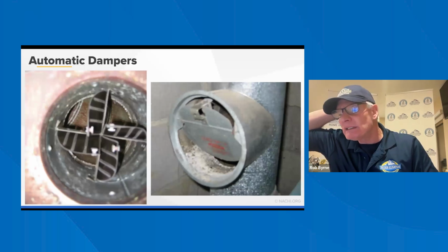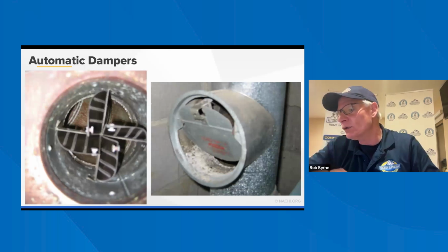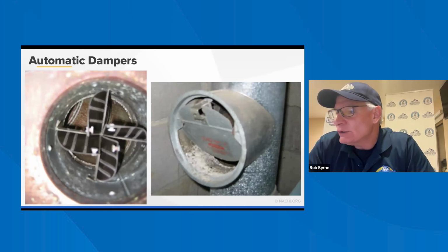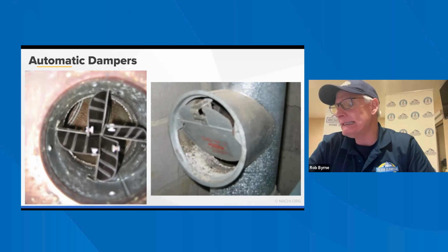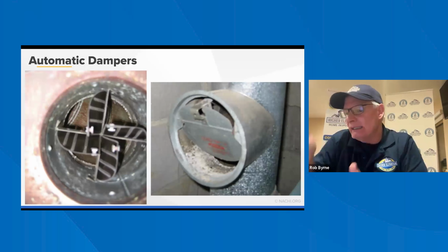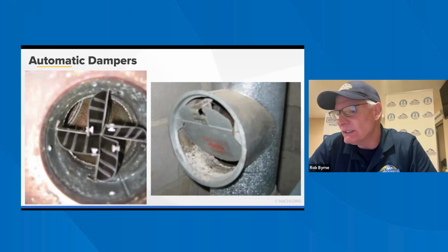Automatic flue damper is an energy-saving device that closes off and restricts flow through an appliance when the appliance is not operating and is in the off cycle. Right, so like I said, it closes and then it does its thing. That's the automatic one. Manual damper should be used only with a solid fuel burning appliance and not with a gas fired appliance.